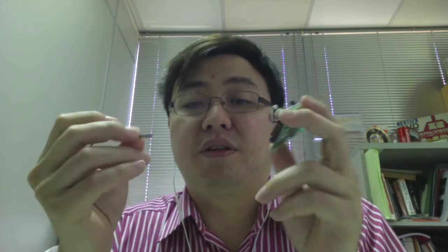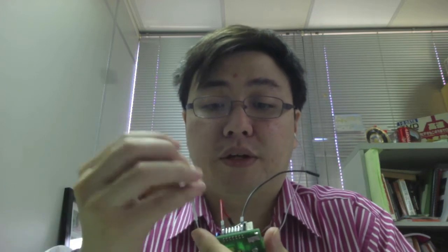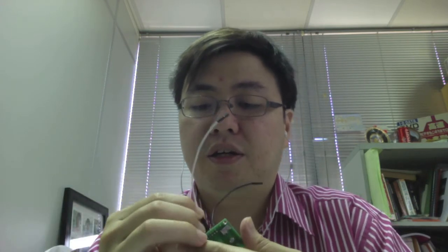Well, the connection is quite tricky. You have to look at the pins. So what I will do is use the black wire and the red wire, red for VCC and black for ground. And I use three white wires for signal. First I connect the VCC, then I connect the ground. So just take a look at it. Be careful with that. And I have EN, IN1, and IN2. Alright, this is how it looks.